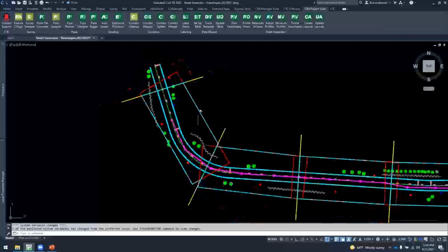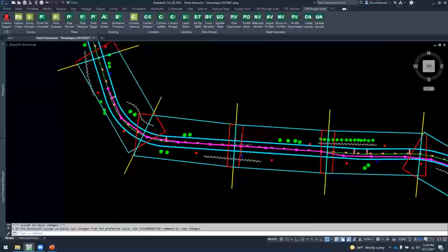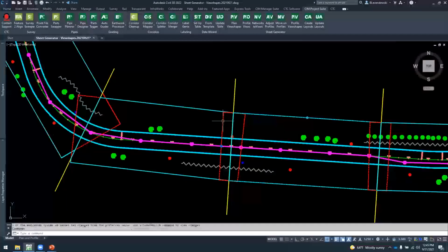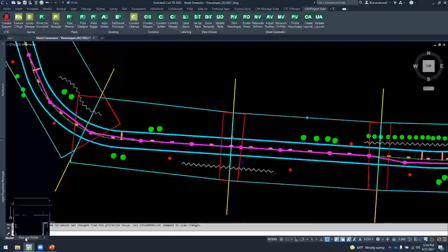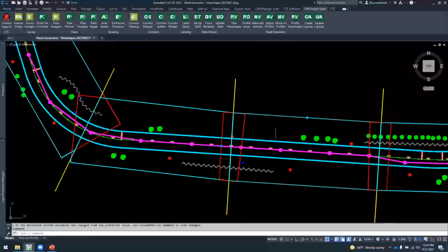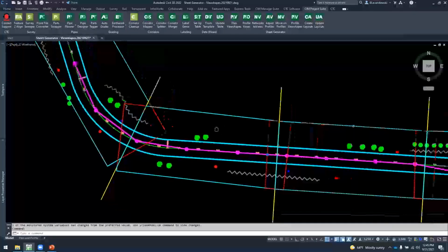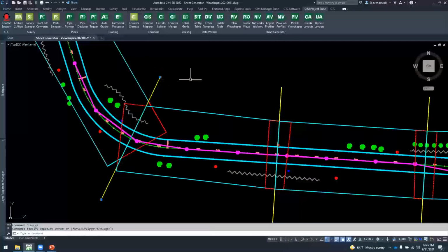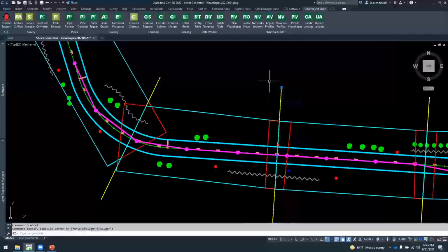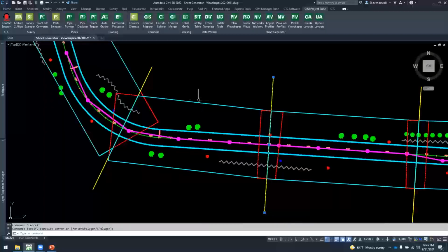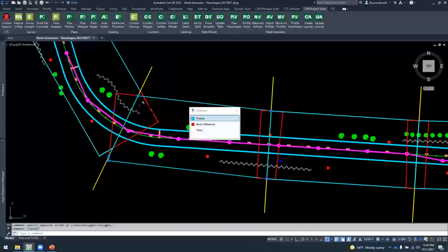So this is laying out our model space. Okay, so what the tool did was take that block that I had on my layout tab down here, scale it by the scale I gave it, and then place it along my alignment based on the insertion parameters I gave it. And then these are my drafting guides. These are just simple polylines. And then from there, the tool is creating a polyline that will represent my viewport in my actual layout tab.